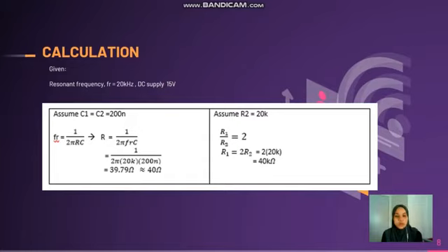Then to find the ratio of the amplifier resistors, I'm using the formula of gain, which is R1 divided by R2 equal to 2. For oscillation to commence, the value of R1 over R2 should be made slightly greater than 2. So I put the formula of gain equal to 2, same as in lab 4 before. So I assume R2 is equal to 20 kilo. Then I got the ratio value R1 is 40.